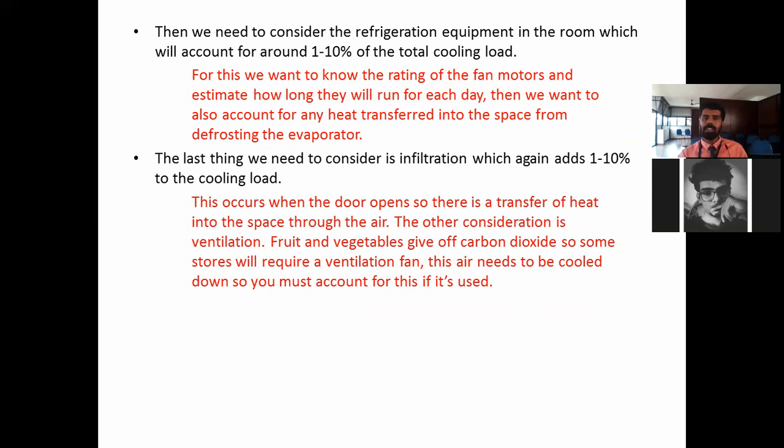The last thing we need to consider is infiltration, which again adds 1 to 10% of the cooling load. You know already what is infiltration, right? This occurs when the door opens. So there is a transfer of heat into the space through the air. Outside air can come inside through infiltration. Sometimes when the door opens, there will be doors in the cold storage, big warehouses. Each time you open it, there is a chance of infiltration of the air from the outside to the inside.